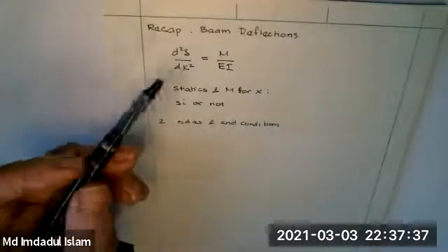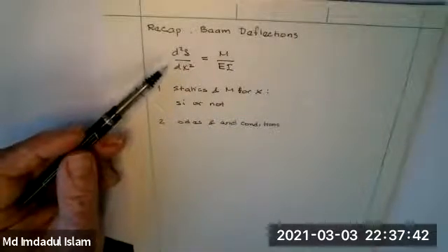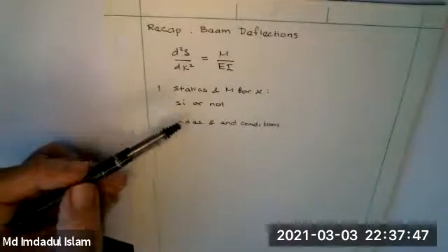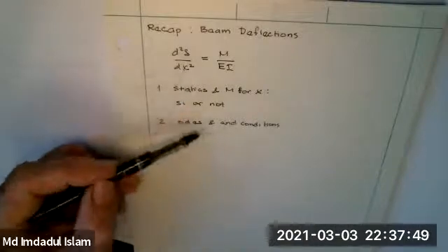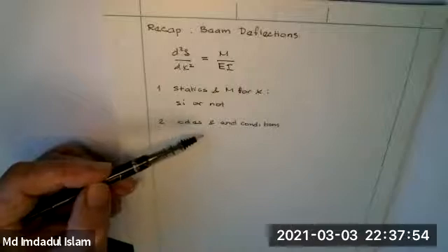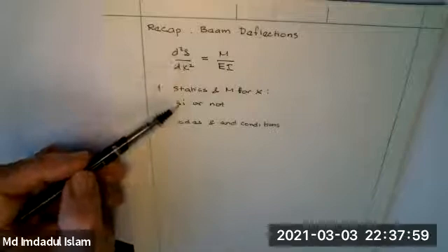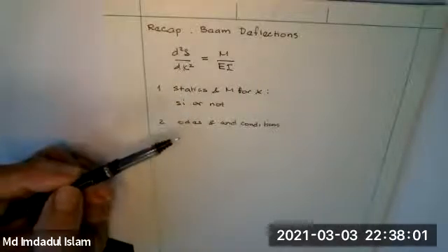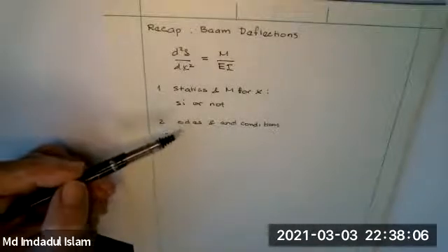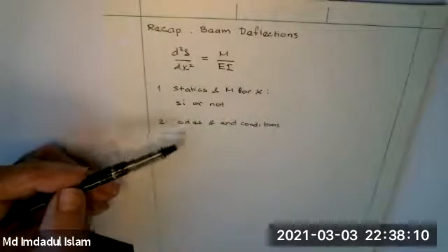You're going to write down your ODEs like this, and each of these will require 2 end conditions. Then you have to have extra end conditions to recover these statically indeterminate terms. So you're going to know the sum of the end conditions, and there's no point in proceeding until you've got a well-posed problem. A well-posed problem is the number of end conditions equals the number of constants of integration plus the number of statically indeterminate variables. Some people start solving the problem, then go along and put the end conditions in as they're going. It's much better to think it through at the outset.